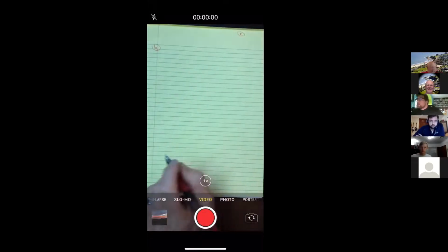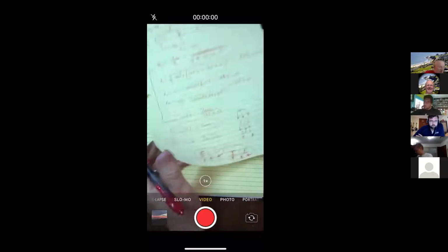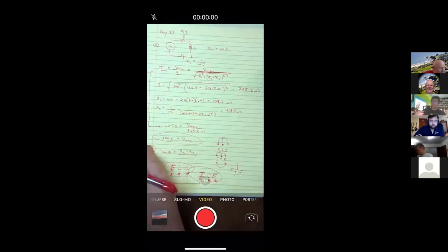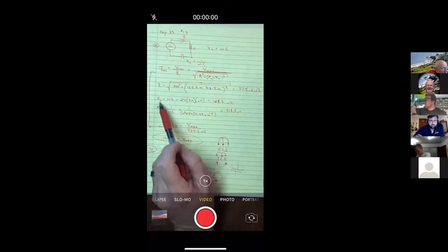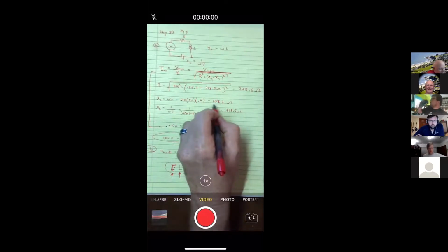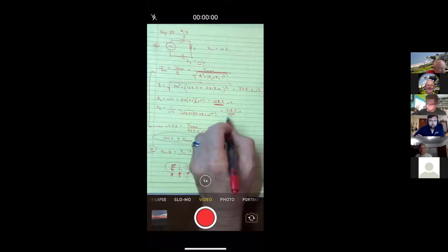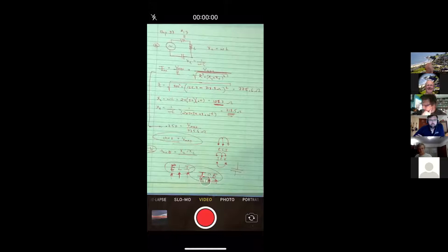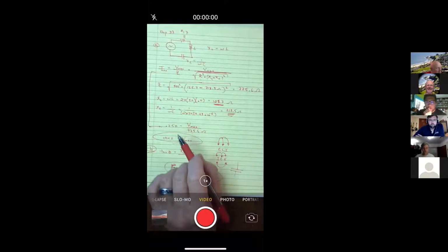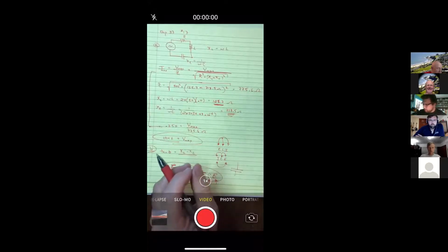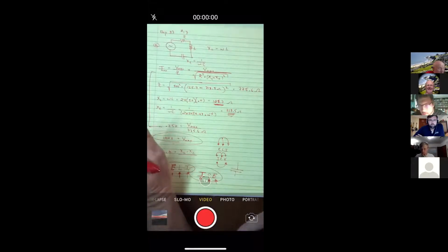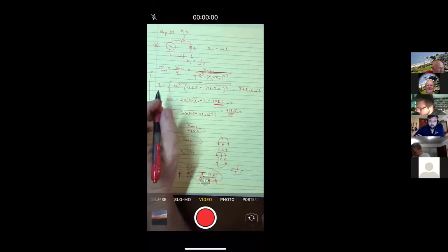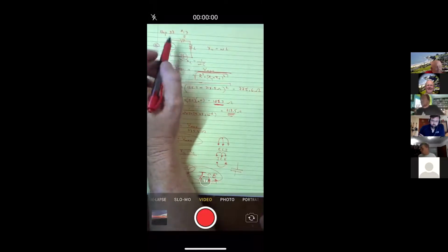Okay, so back to this problem, and I have to go here to page 2. But you could have even seen it in the numbers. I should have pointed it out here. As I was looking at this, I realized that the reactance of my inductor is much smaller than the reactance of my capacitor. So that would tell me that this circuit is being mostly opposed, if you will, from the capacitor. And that tells me something really important here.